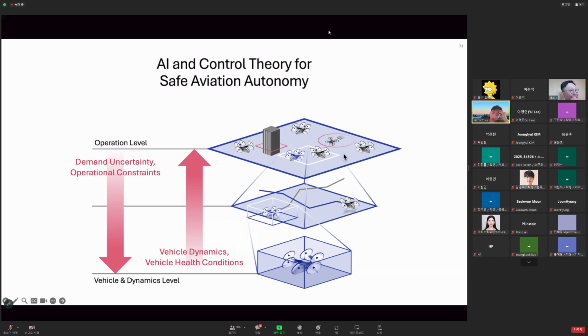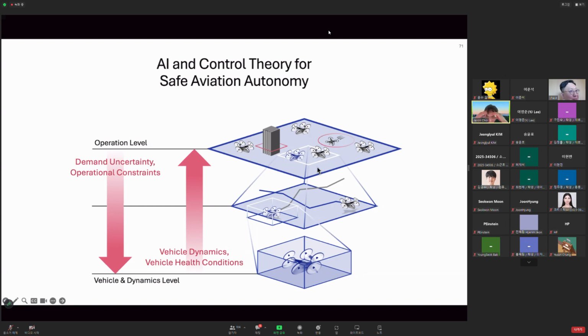That's a very good question. Actually, I have one agent here. If you look closely, I'm marking one agent as an adversarial agent. This red agent is some adversarial agent that these other vehicles have to avoid. The nice thing about the reachability framework I showed you today is that it can be formulated also for the non-cooperative case. For example, we can add an adversarial agent to our dynamics. Now that becomes a game problem instead of an optimal control problem. In this game problem, we can compute the region from which our agent can win against the other agent, meaning in terms of safety, we can still guarantee safety despite the adversarial actions of these other agents. So I would say these frameworks can also extend to such non-cooperative or adversarial settings.